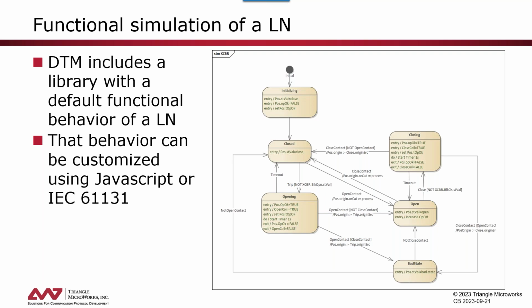There is somewhere in the standard where the limitations are defined, but the limitation is such that the total of your logical device name, which is created by the ID name and the logical device instance, should not be more than 64 characters. So I think the ID name can be way bigger than 6 characters.